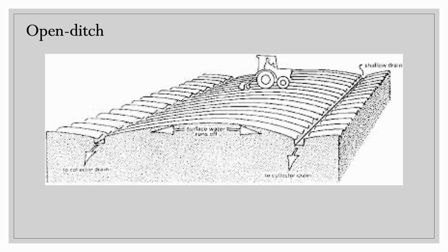And so, when I'm thinking about this picture of an open ditch, I'm thinking like a football or a soccer field. If you've ever noticed a football, or especially a soccer field, because they're much bigger, there's a slight crown down the center of that field such that the water gently moves away from the center off to the sides, and then there will be this drainage ditch that allows that water to move off site.